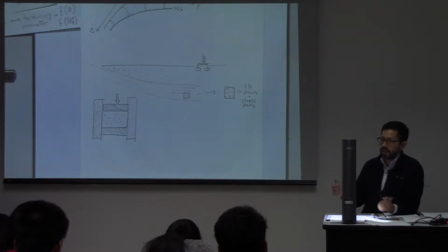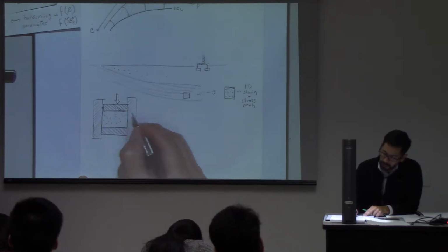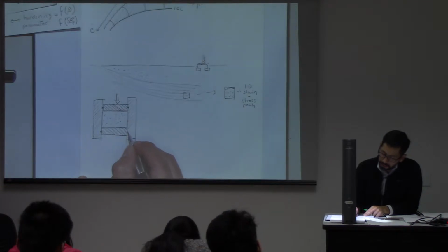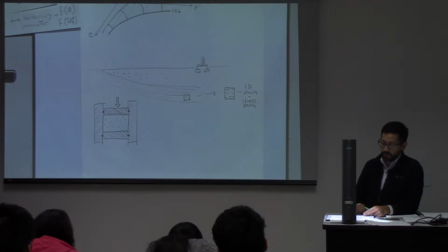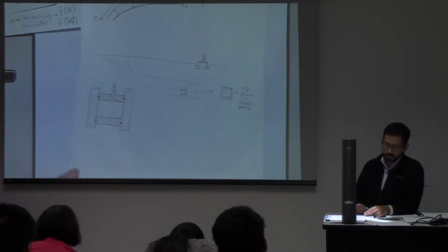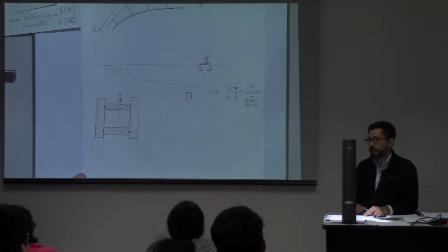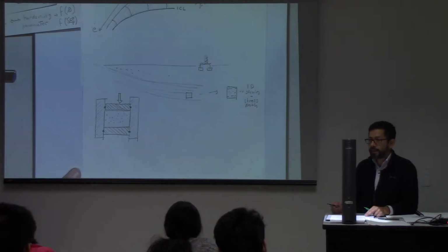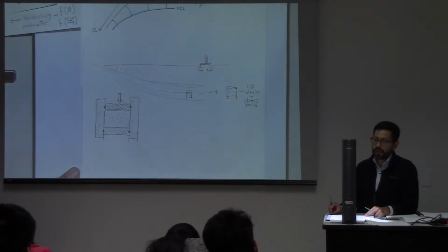If I compress it, and I'm going to tell you a little bit more, I'm going to put an O-ring over here so that the fluids cannot escape between the walls of the steel vessel. If I don't let the fluid escape, it's not going to compact. I'm going to measure the undrained constraint modulus, and that's not what I want to measure.